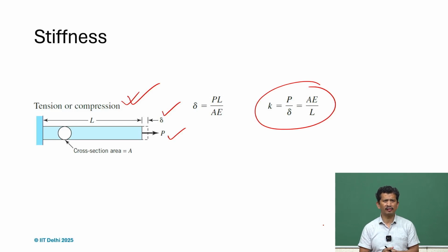That is why we always say to try to design so that the loading coming on the members is always in the axial direction, either in compression or tension, and tension is much better. In compression we also have to look at the buckling phenomenon, the instability. If it is in tension it may not be a problem, and that is how tensegrity is designed.